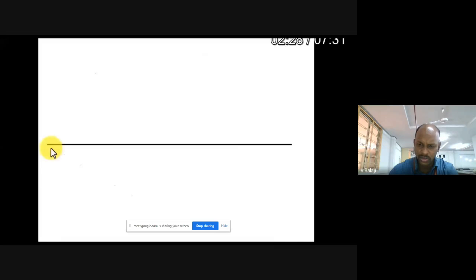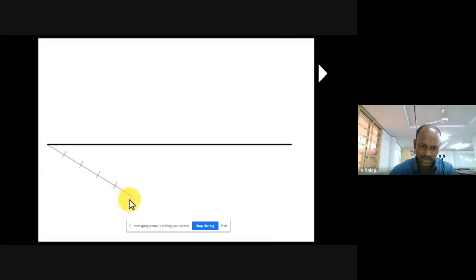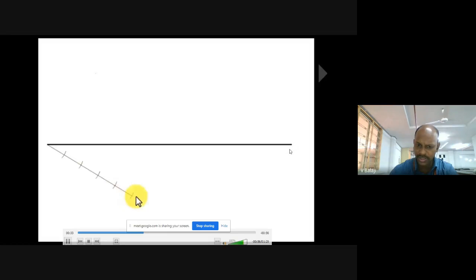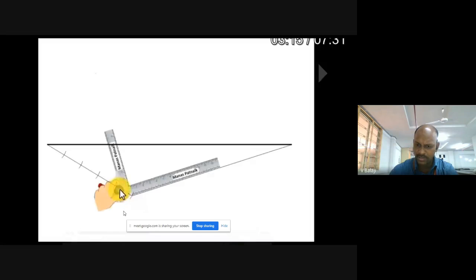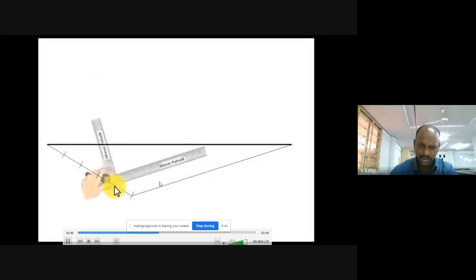Then how to do that 5 equal parts? You know, right? You take a line of any angle, any length, right? Take your compass, draw 5 equal arcs. You know what is the next step? Join the last arc to the other end of that line, with the help of a mini drafter or ordinary scale. And now match one of the mini drafter scales to this particular line and tighten the mini drafter knob. Draw parallel lines from every arc. Okay, like this.